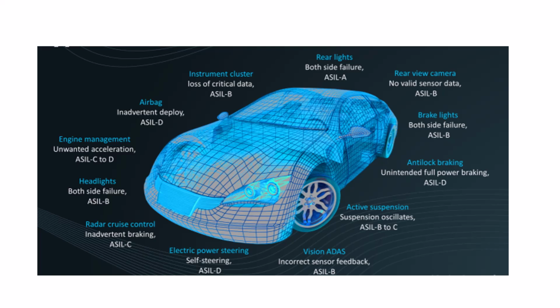The acceptable failure rate, as far as I know, is 1 in 10 to the power 8. That is for ASIL D, the highest rated, which covers your airbags, your steering and all these things. For non-automotive people, what it means is your airbag should work in any case, and the chance of it not working is next to zero.